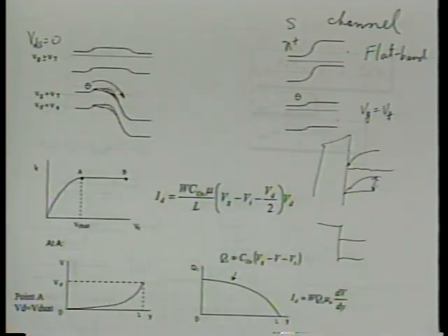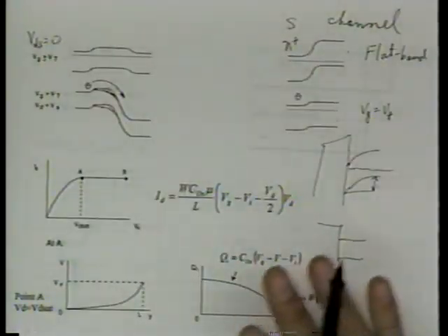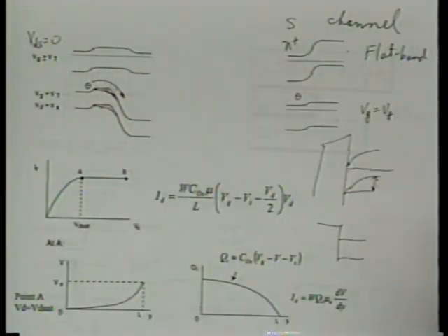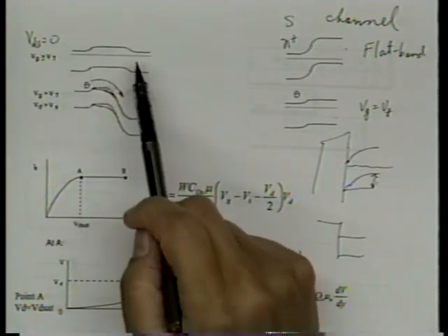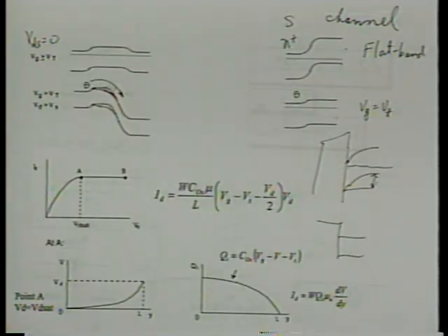Drawing a Fermi level in a non-equilibrium case is always difficult. Now, what does equilibrium mean? Well, when there's no voltage applied throughout the system, then it's easy. It's an equilibrium. We all know that. Even in this case, we can still say it's equilibrium, because even though there's voltage applied to the gate, just because the gate is such a good insulator, we don't have any current flow, we don't have energy exchange, that's equilibrium. All right?